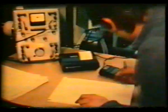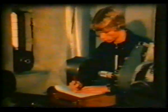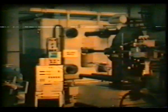Here, the expansion of the tie bars is being measured by the so-called strain gauge test. And here, the shot unit is being accurately aligned by means of an optical alignment instrument. Finally, each machine is subjected, together with the control system, to a 100-hour endurance test at maximum load to eliminate potential sources of failure.